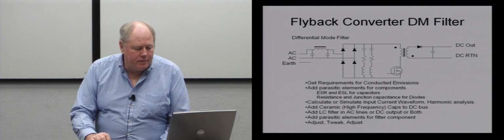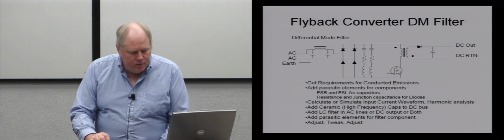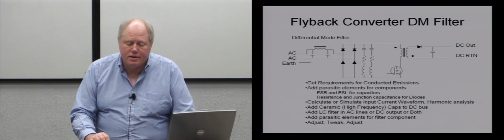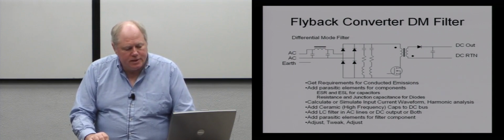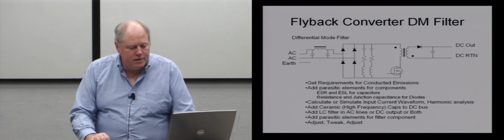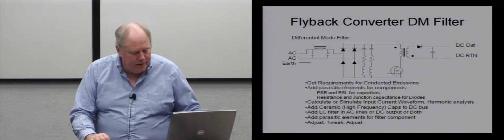There's a capacitance that's going to shunt your inductance and let the high frequencies go past it, and the same with the capacitors. There's some resistance and inductance that's going to limit the high frequency characteristics of that. But basically, what you're trying to do is make it so all that switching noise stays inside the power supply and doesn't conduct back through the utility.